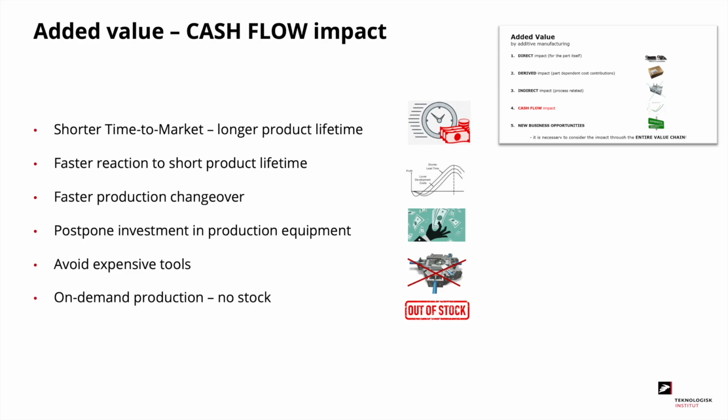You could also have faster production changeover. If you face high investment costs for production of a part, you may postpone that by starting with additive manufacturing of the part. You may avoid expensive tools, and finally you may produce on demand, meaning no stock.